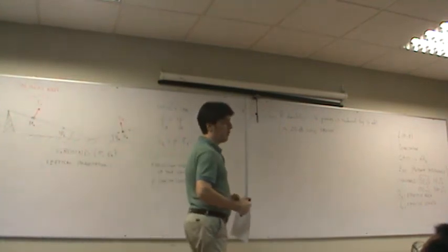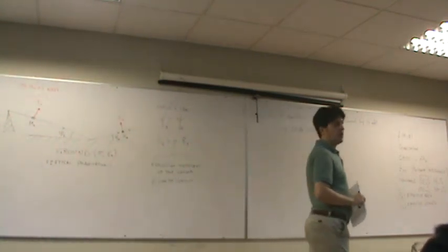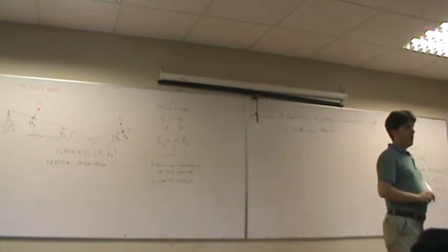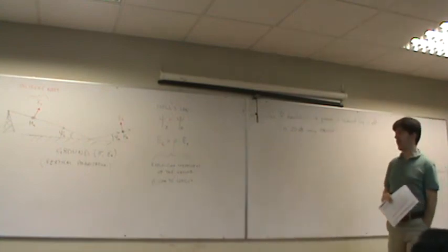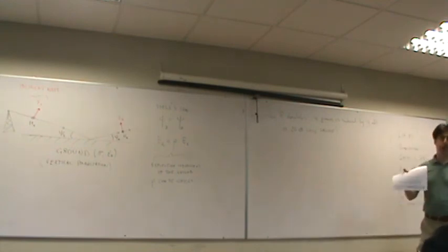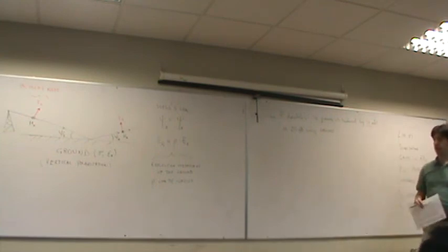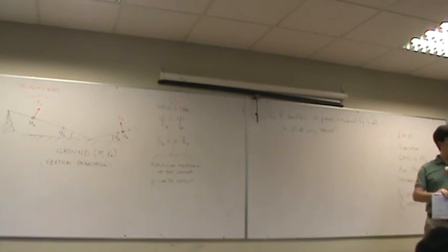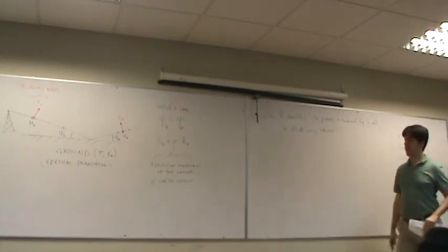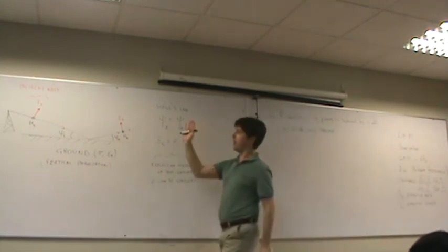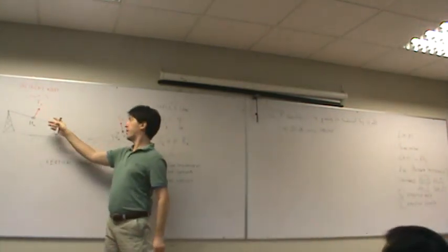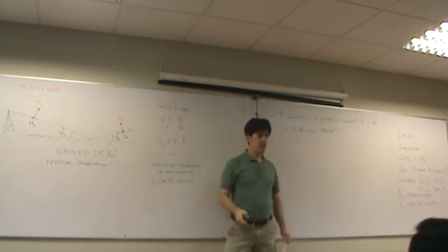You may say, well, but the electric field is not vertical with respect to the ground. And in fact, vertical polarization is not strictly correct, but it is the orthogonal polarization with respect to the horizontal polarization, where the electric field is effectively horizontal with respect to the ground. So the electric field is not vertical, but this is called vertical polarization.